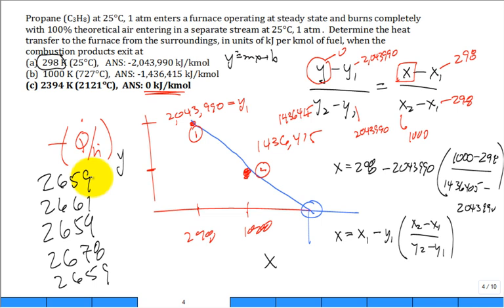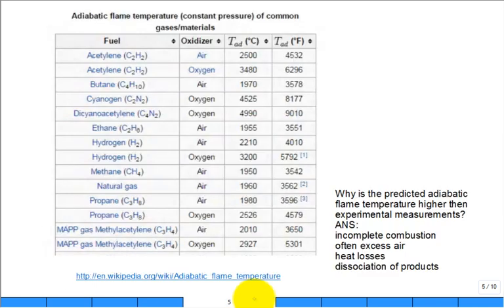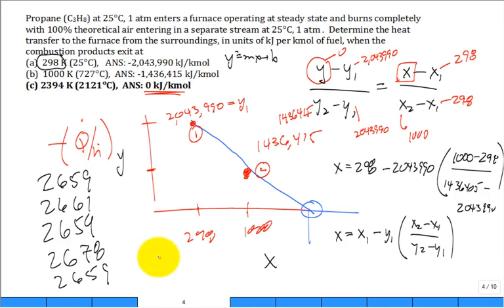All right. So where are we at for time? It looks like I got about 4 minutes left, right? So this is the adiabatic flame temperature. You know what? Using our tools, we can go out to the internet or textbooks and we compare with reported values. What did we just do? Propane with air. And we just got the adiabatic flame temperature not to be 1980, but to be 2,120. You say, oh, that's a big difference.